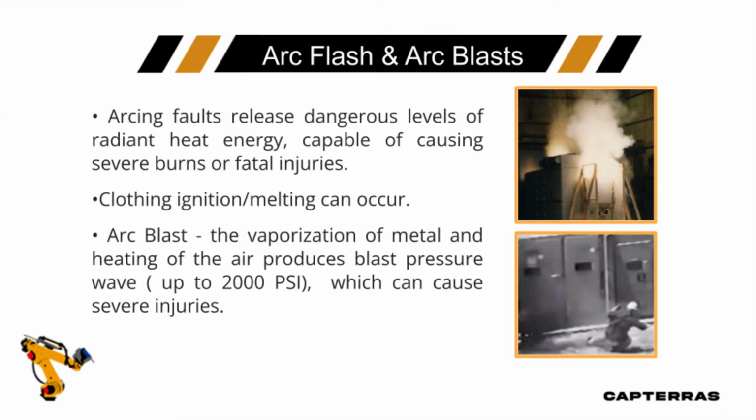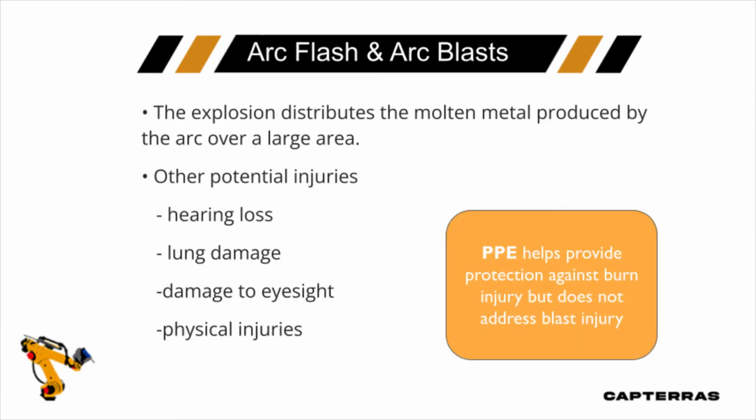So when we look at PPE, we also have to consider that PPE protects us against heat, but it does nothing to protect us against being blown back. In other words, the blast pressure wave may cause internal injuries, and or it may cause us to be blown back against something that's sitting behind us. So one of the key things to think about when we're doing energized electrical work, depending on the level of magnitude of incident energy, is where are we going to be blown back to? What's behind us? Because our PPE is not going to protect us there. Maybe a hard hat would help protect our head to some degree, but again, we could fall back against a sharp object. So we need to think about that.